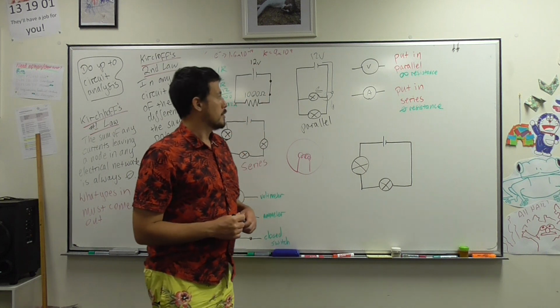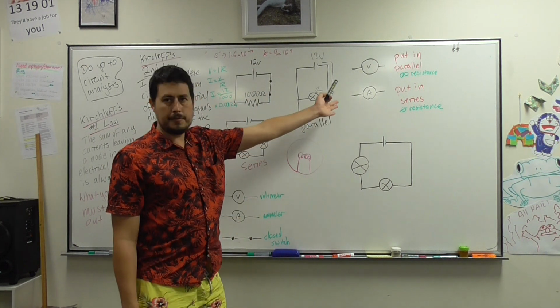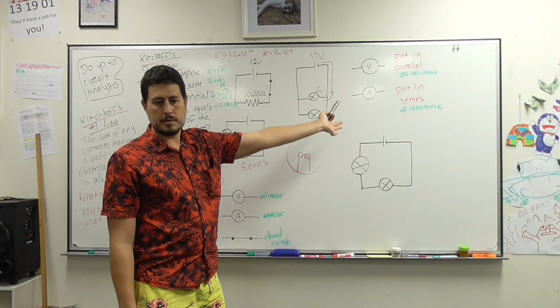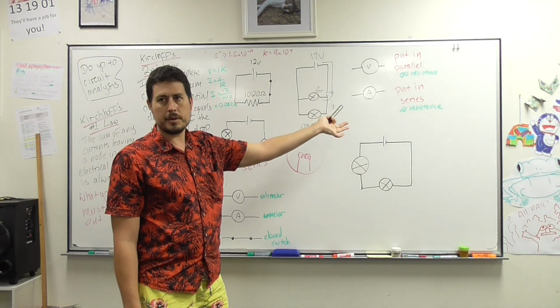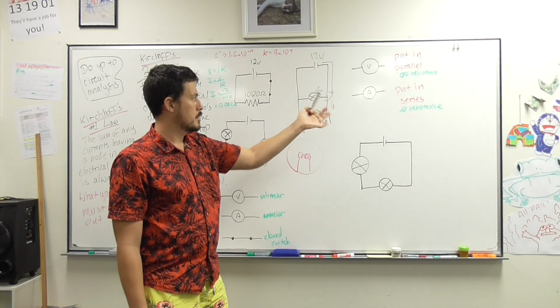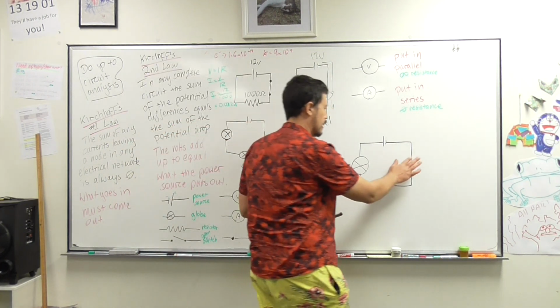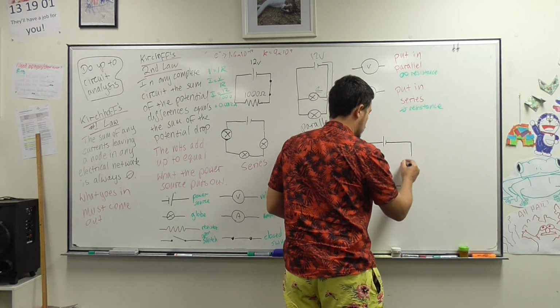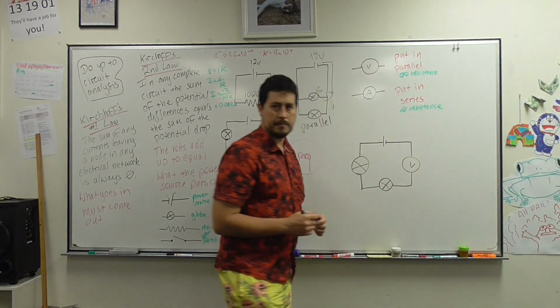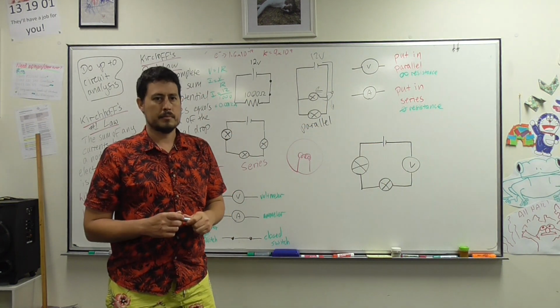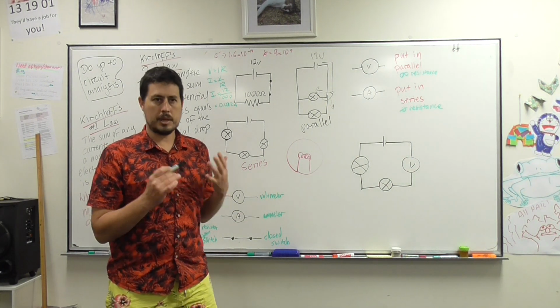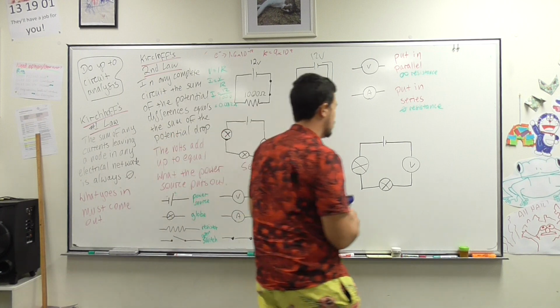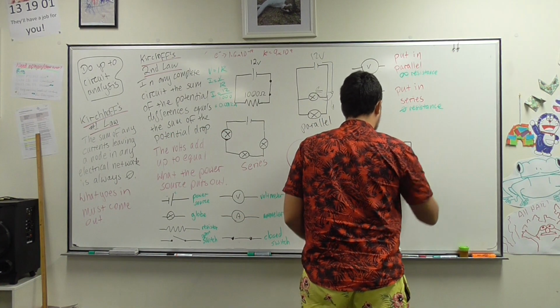When we're measuring volts, the voltmeter has an infinite amount of resistance. It's not going to let pretty much any electrons go through. A few will go through, but very few. So if you stick the voltmeter here, what's going to happen? The light would just stop. It wouldn't work because it's got infinite resistance. It's important that it has infinite resistance because